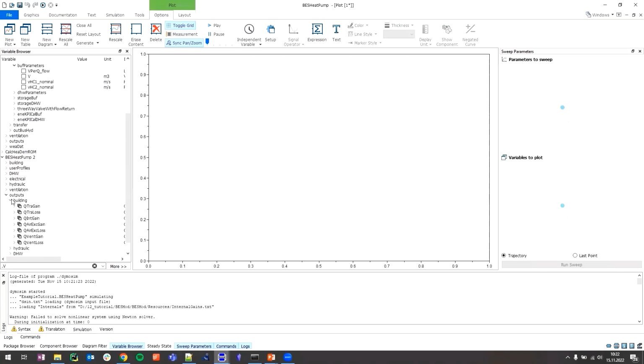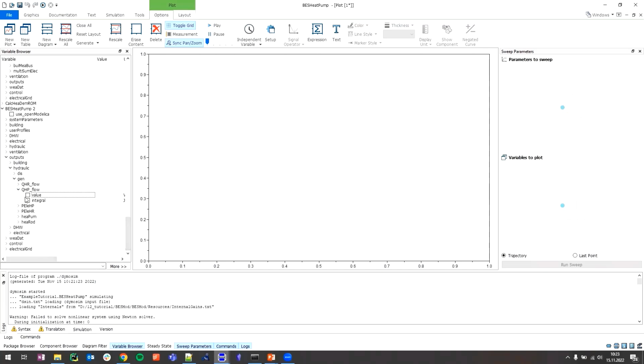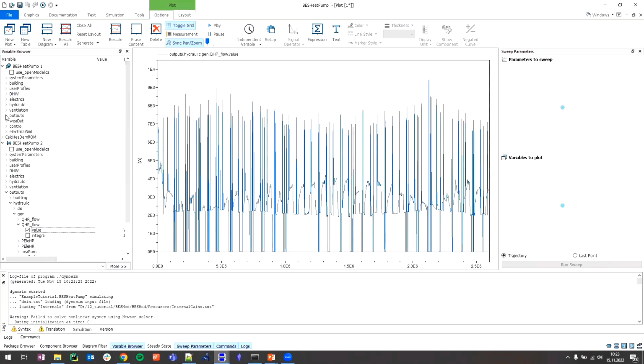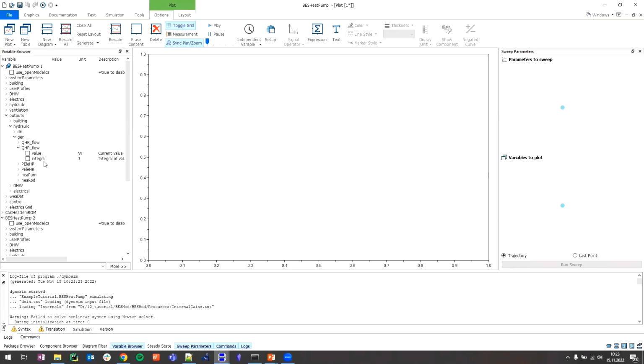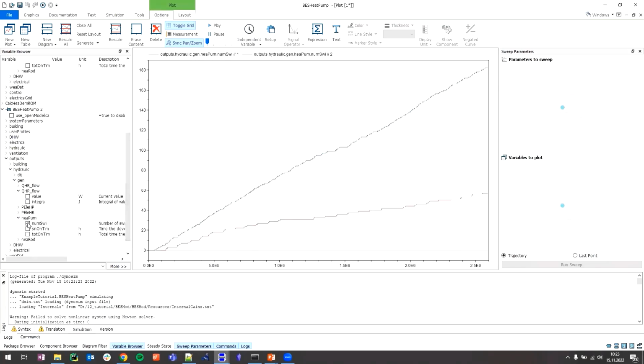And now if we look at how the heat pump behaves, we can see that without this option, the value is a lot more continuous. So let's compare it to the simulation before. We definitely see that the first oversized heat pump led to a lot of switching behavior. It switched nearly 180 times in the winter, and now we only have 60 switches. So reduced it by factor 3.